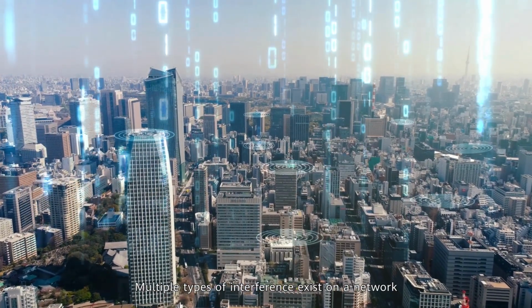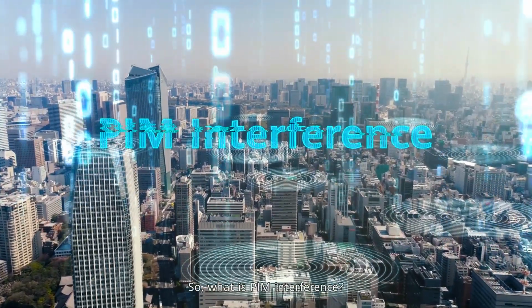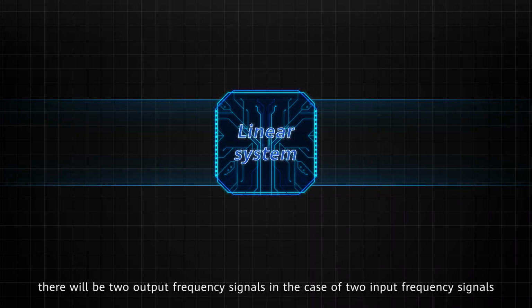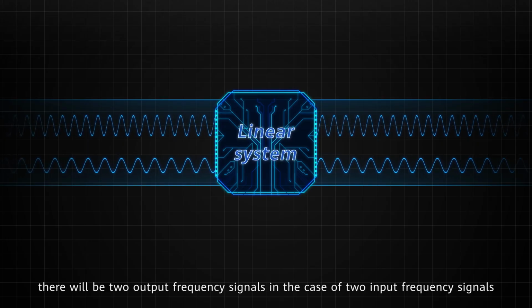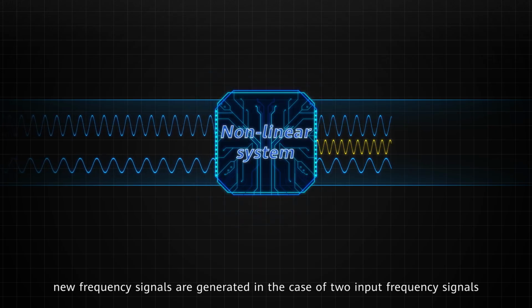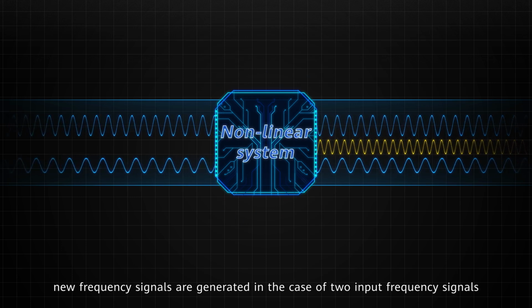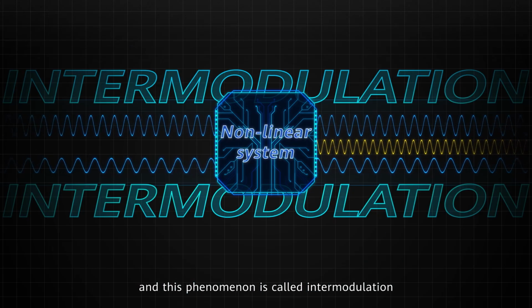Multiple types of interference exist on a network, one of which is PIM interference. So, what is PIM interference? In a linear system, there will be two output frequency signals in the case of two input frequency signals, and no new frequency signal will be generated. However, in a nonlinear system, new frequency signals are generated in the case of two input frequency signals. The new frequency signals are known as intermodulation products, and this phenomenon is called intermodulation.